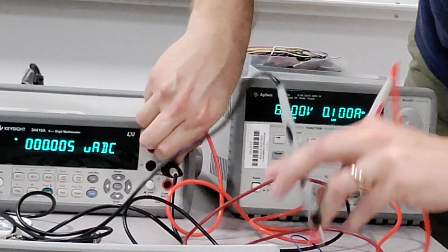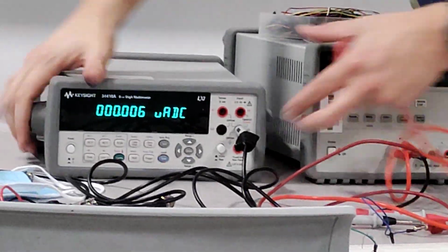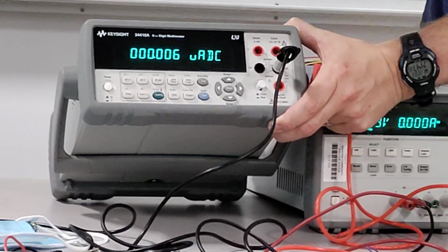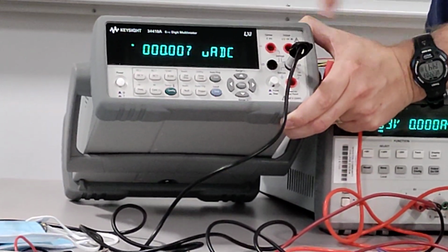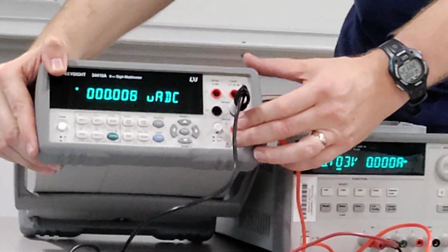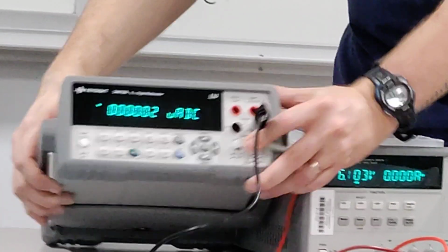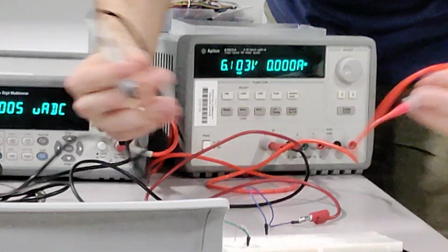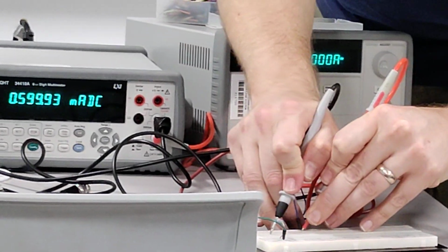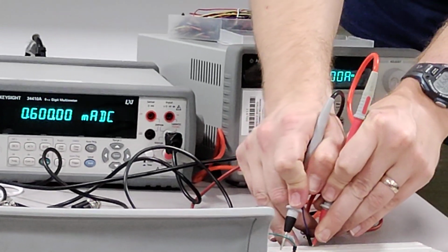Another basic mistake that I just made, and everyone else is also going to make, is that the symbols above this hole show it's for voltage, resistance, capacitance, and diode forward voltage drop. If you want to measure current, you need to bring the red down to this bottom one. Super important. We all saw that does not work, right? It's not going to work for you either. So now I'm looking at 0.599 milliamps, which this power supply wasn't even able to measure, but the multimeter can.